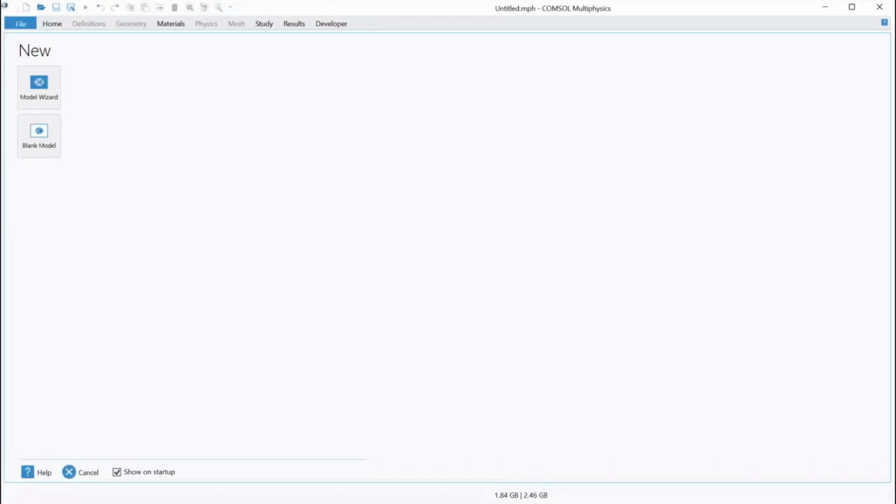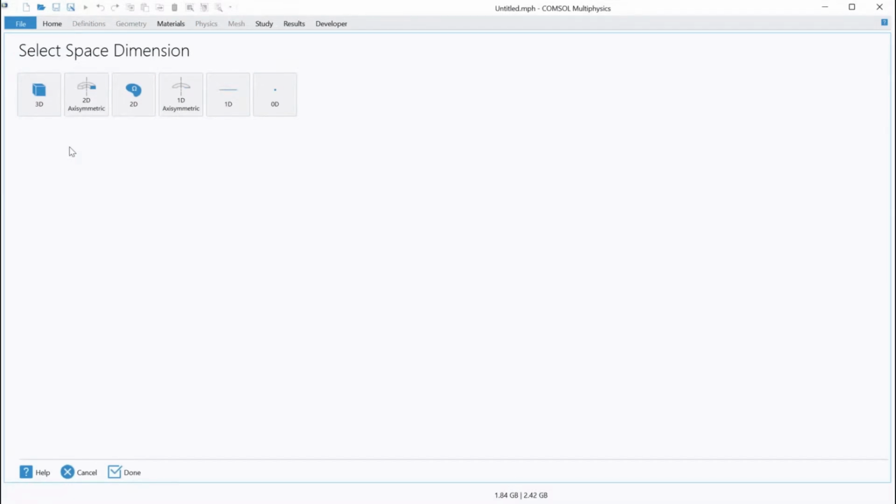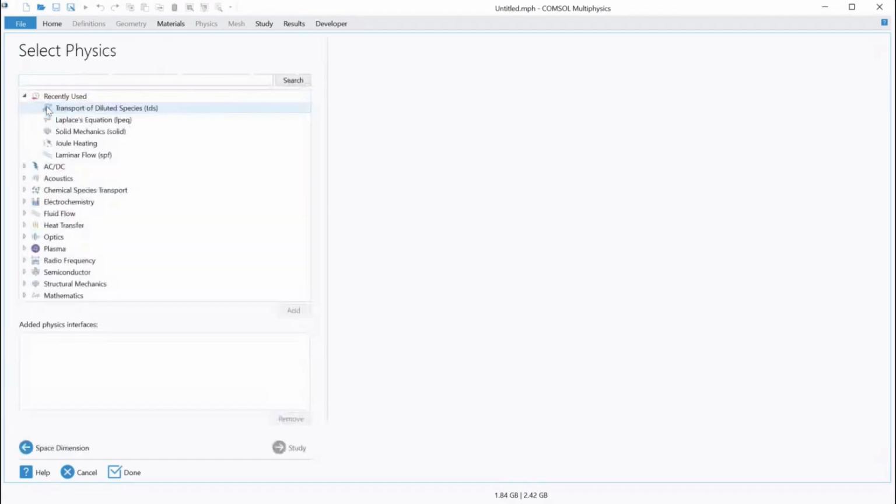For this demonstration, I'm going to assume that you've seen COMSOL before in perhaps more elementary webinars, but still, let's walk through this step by step. So we're first going to choose the model wizard, since it just helps us take the first couple of steps. We can work with several space dimensions. And if we have a problem that allows for, let's say, exploiting symmetry or looking at it from a side view or whatever you want to call it, then it can be very efficient to use less than 3 dimensions. But in this case, we'll stick to 3.